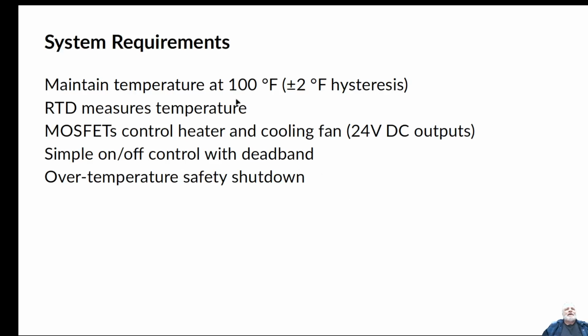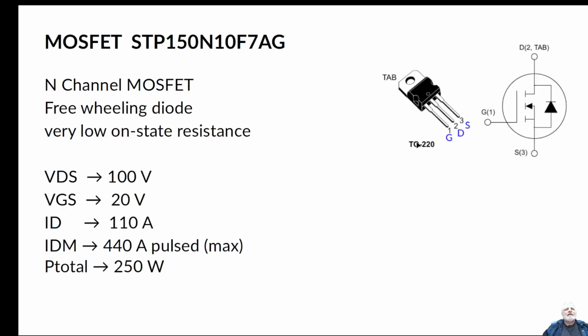All right, so we're going to use this MOSFET here. Here's the part number. I'm not even going to read that, but here's the wiring for the MOSFET. This is actually already pre-wired for you on the box, and the box is marked. We only have to worry about basically powering the gate and getting 24 volts to our resistors and things, and just power the gates to turn these on and off. We also have some temperature sensors already inside of this that we could also wire up and monitor.